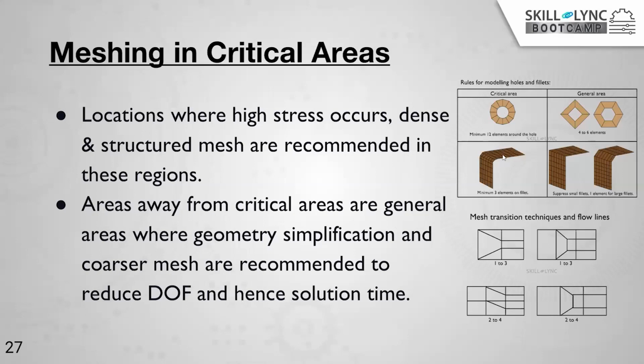Now, suppose you are modeling a fillet. In that case, you should be modeling a minimum of 3 to 4 elements along the fillet so that you are able to capture the curvature properly.